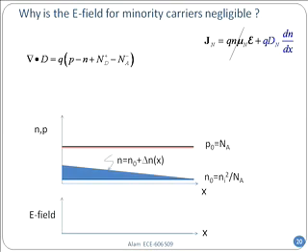So you remember that in the middle section, light was shining. It generated electron-hole pairs, G multiplied by tau sub n. That was the extra carriers. And it was sort of coming out in region 1 and region 2, the contact sites. It was coming out, and let me assume that it was coming out in the trap-free region with a linear profile.